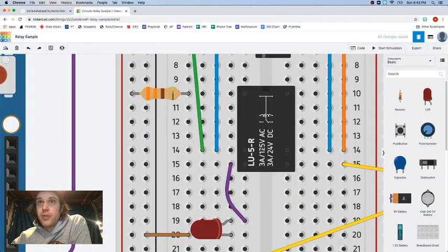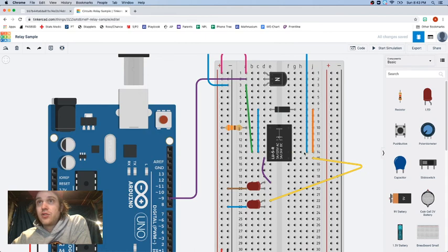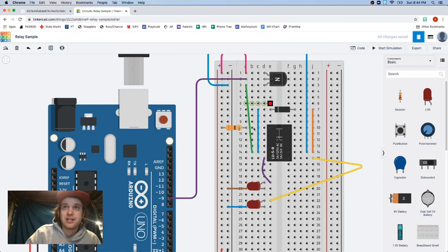We're going to charge up that coil, which is going to create a magnetic field, which will suck that over. Then the electricity is flowing through, and it returns to ground and goes home, okay? So when electricity is running through there, this flips. Electricity goes to here, opens this, electricity comes through, flips that, and when that shuts down, the magnetic field collapses, and our electricity dissipates in our flyback diode.